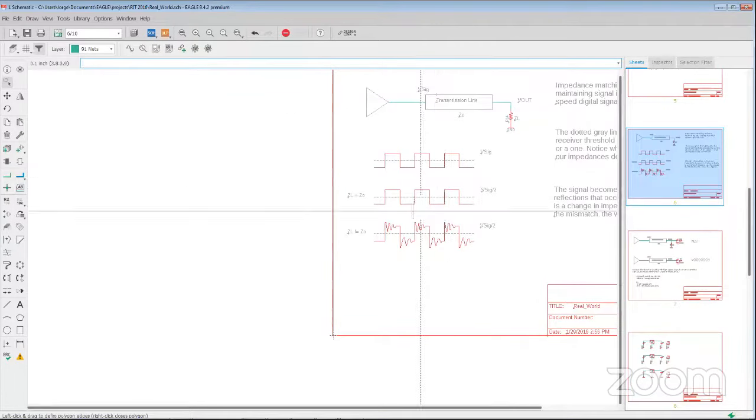Especially when you're getting started in electronics, almost all the signals you're ever dealing with are changes in voltage. So in that context, we're taught that you want to have low output impedance and really high input impedance, because that way the voltage doesn't drop when you're transmitting it, because that's the signal of interest, voltage.